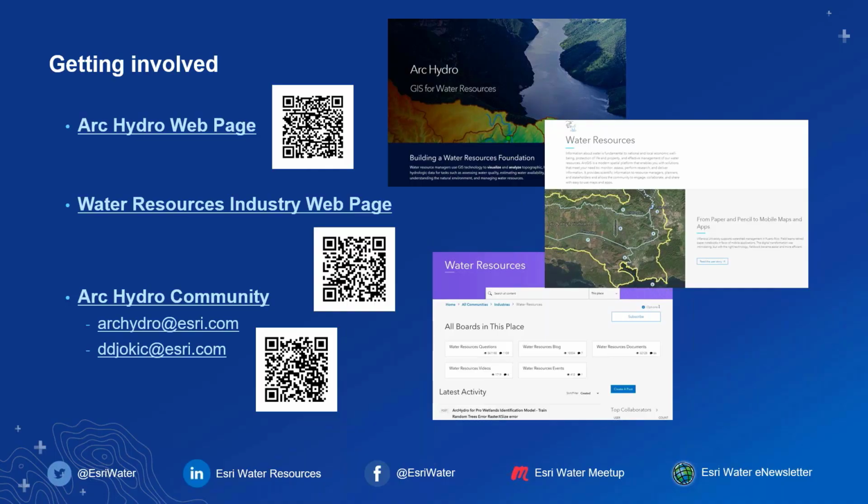There are a couple of ways to do that. One is to build your own rainfall distribution, where you stack the storms up back to back. Another way to do it is to run one storm and then put in a delay in your basin data.